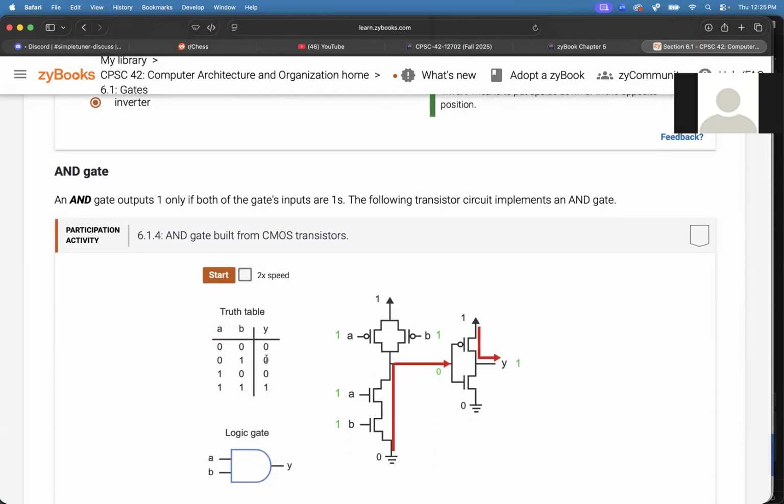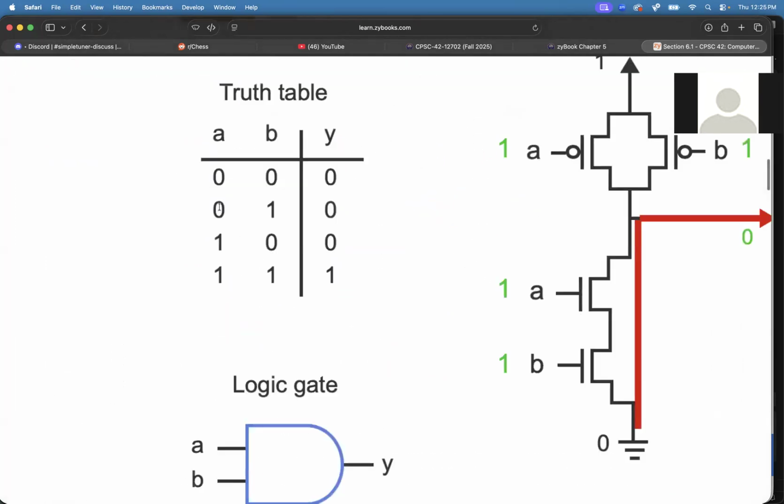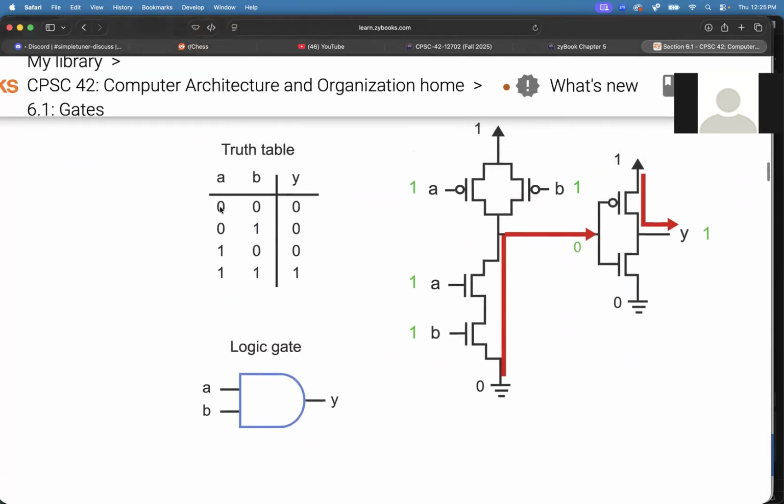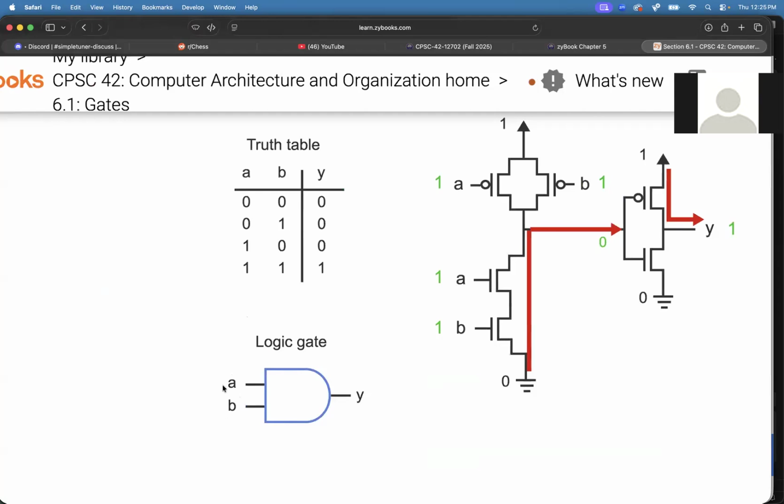And then we get to the AND gate. So the AND gate truth table we should also be familiar with. An AND gate, which has this symbol, has two inputs and an output. So you need to know the inputs A and B, both of them, before you know what the output is. When the inputs A and B are 1 and 1, then the output is 1, and every other combination gives you a 0.